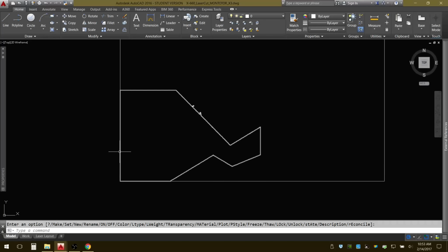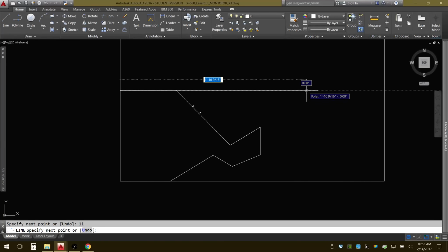Now I could keep this on, and I'm going to try. This is what I was having difficulty with before. Well, AutoCAD was crashing on me, but we'll see if we can get somewhere. I'm going to create a line. Again, my object snap here is just going to highlight that corner at the endpoint, so I can then go up, and I want to go up 11 inches. I'm going to go over.